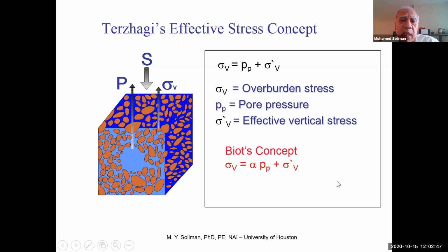So they said there is a factor here that is usually less than 1, which is the Biot coefficient. So rather than assuming it's 100% efficient, we use partly efficient. That constant is anywhere between 0.7 and 1. It depends. Most people will probably use about 0.9 or so. But it is important to measure that parameter, especially if you're going to look at sanding. That is very important to do.